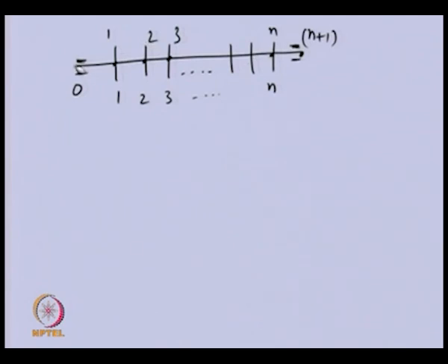Now, let us start with the left side. The field variable corresponding to station 0 is, let us say, S naught, because here there is no disk. So, we are not attaching any left and right of the disk, but we are just saying it is a field variable corresponding to station 0. Here we can have the state vector, that is left of disk 1 as well as right of disk 1.